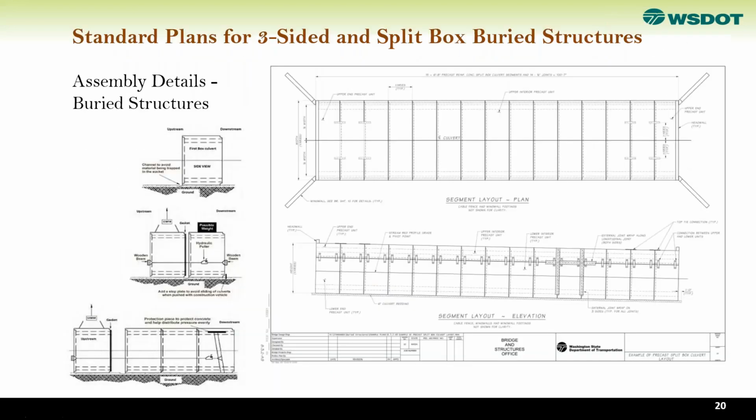And this is for the assembly of the buried structure. The main thing, when you bring these precast segments to the job site, is to have good bedding quality, which I'm going to talk about, but also a method to put these together in order to have a uniform joint and uniformity at the top and bottom. So there is not much distortion due to the installation or bedding material and so on.